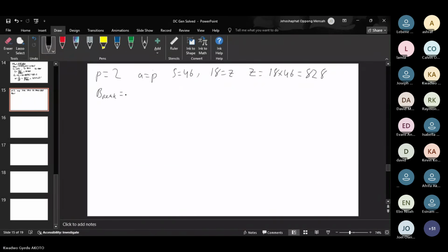And then we know that our peak flux density is 0.7, right? And our field pole spans 70% of our pole pitch, so we have lambda F on lambda P to be 0.7, right?